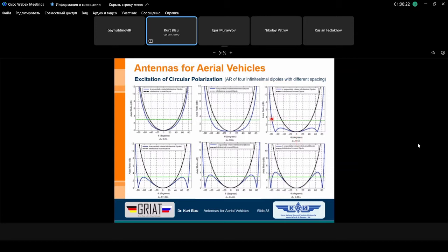And so we can see that we came near 80 degree plus minus, let's say 75 or so, the total opening angle to hold a circular polarization equal or better than 3 dB. It's now, let's say, 150 degree. It's very good.